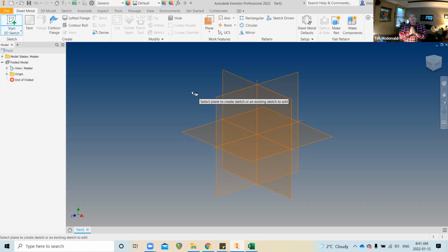If you have a component that could possibly have a variation, something that you might use down the road, or something that might already define an adjustment that you foresee, then creating these components using the iPart tools is kind of powerful. So first of all, we have to create a component.